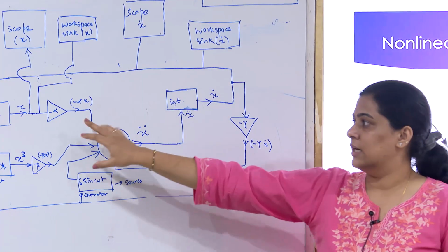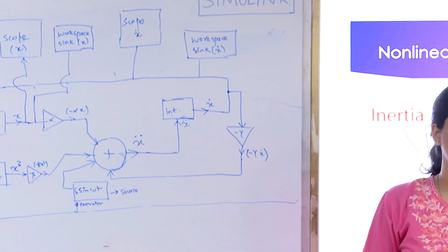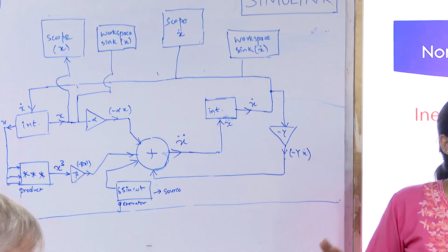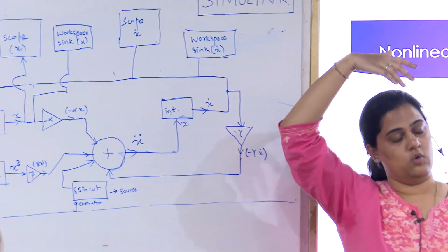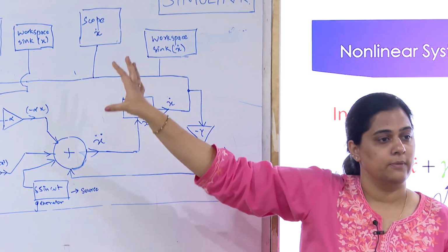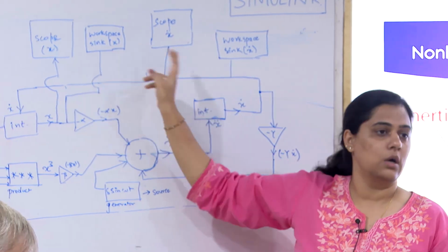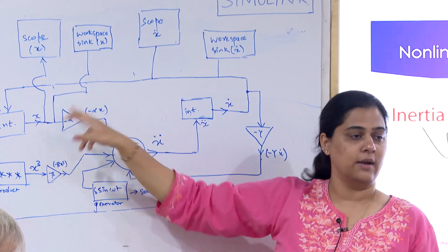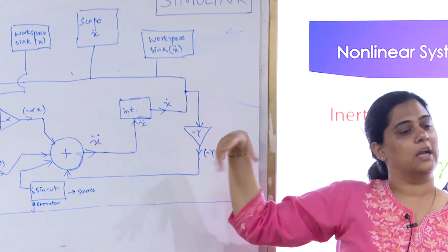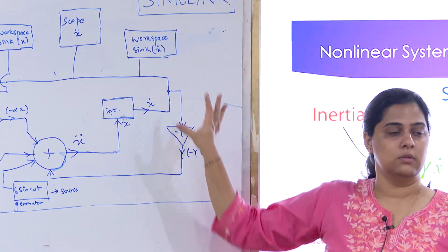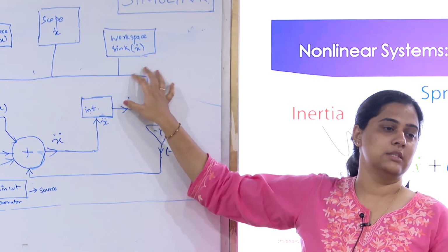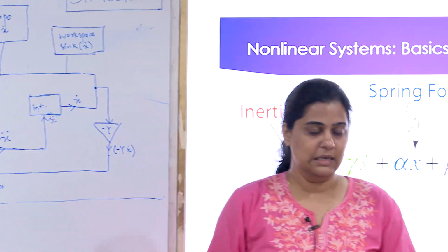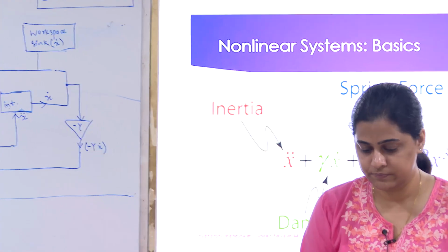Now suppose the simulation is run here in Simulink and x and x dot are being generated. Now you want to take them out to the workspace. You want to save them there. So you need to put a sink. Okay, so you can just put workspace sink blocks. One you can put over the output x and one at the output x dot. So that will save these simulation variables in the MATLAB workspace. Okay, I'll tell you how you can access it there.